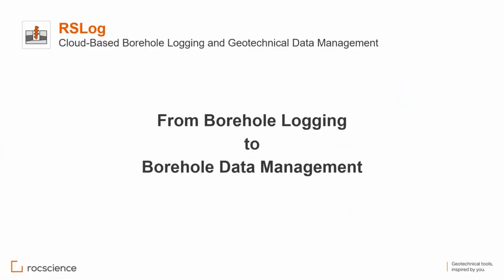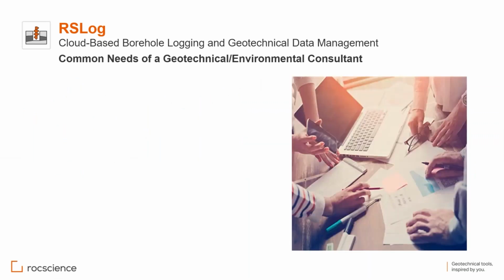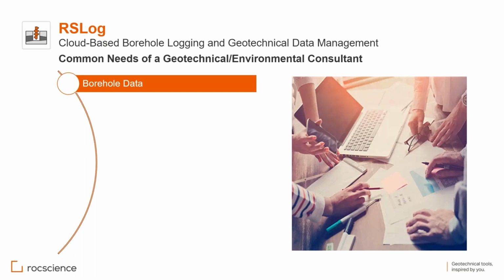Okay, so let's first talk about what type of data you need to collect as a geotechnical or environmental consultant. Obviously, borehole data, that's the basic data that you always collect. This data could be your SPT data, other field test results, soil layers, groundwater level, and so on. And then you also have some photos taken during site investigation. So it could be your core photos, or, let's say, if you're doing slope reconnaissance type of projects, it might be a combination of hand sketches and photos.